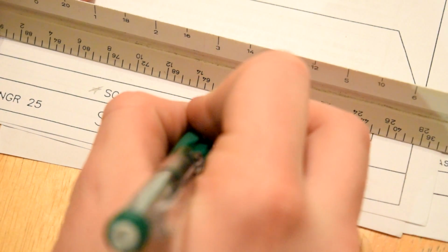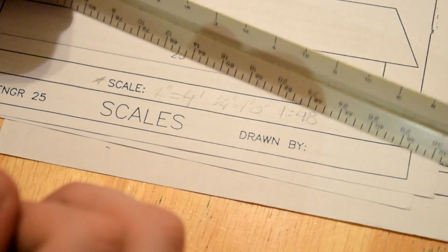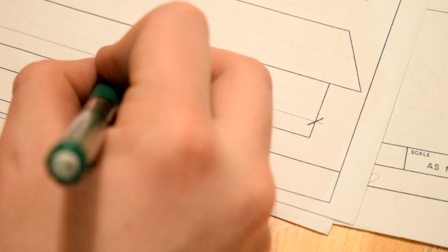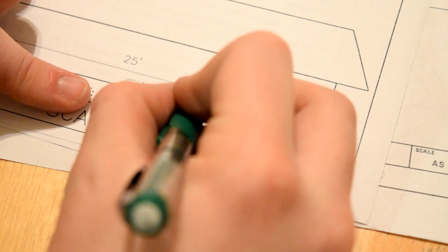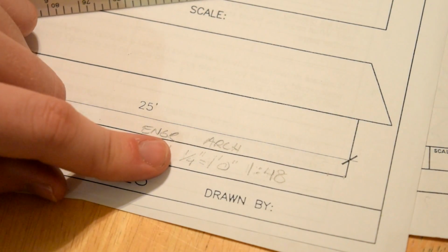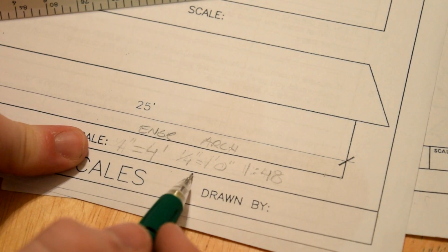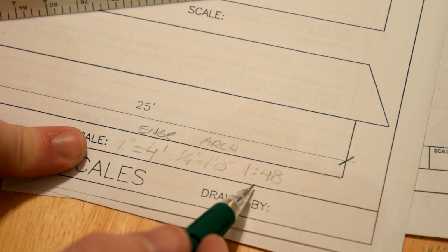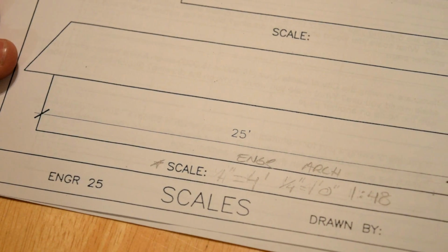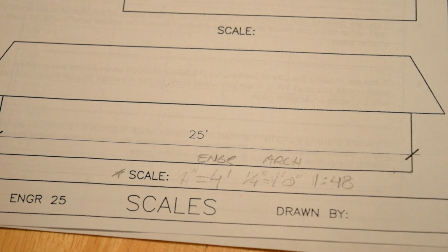So I could have also said that 1/4 inch equals 1 foot 0 inches. So 1 inch equals 4 feet on my engineering scale, or a 1/4 inch equals 1 foot on my architectural scale. And you'll notice that these are the same ratio. With the architect scale I essentially reduced both sides by 4. And again, they're both the same size of 1 to 48. So that was just a few examples of scales. I hope that helped, and again I apologize if you had a hard time viewing this video from things rotating around and not necessarily being in the frame.